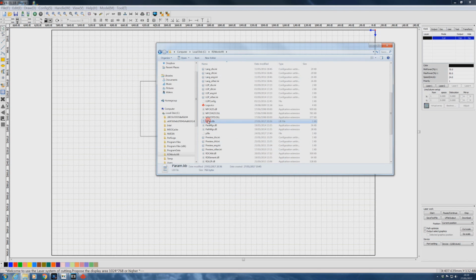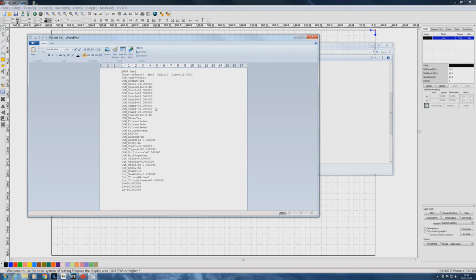We've got to go back to the parameter library, and you'll notice that once we've opened the parameter library with a known program, it'll continue to keep opening for us. So what we've now got to do is to find out where our problem was, and the problem was here in our max and min, and we need those edited to 67 and 67. And now we can save it.